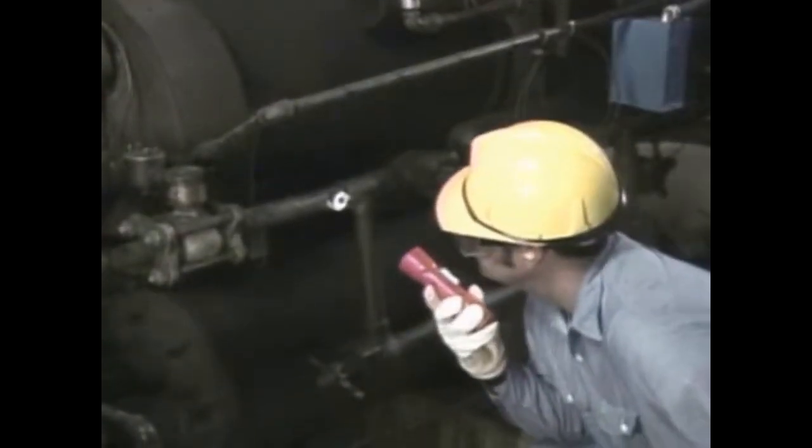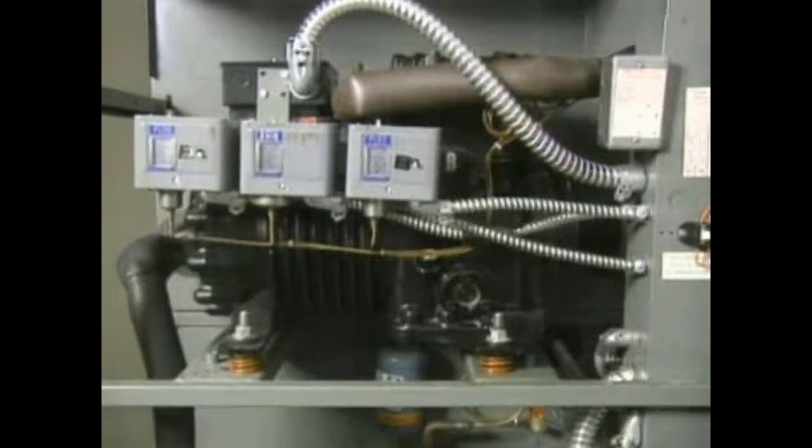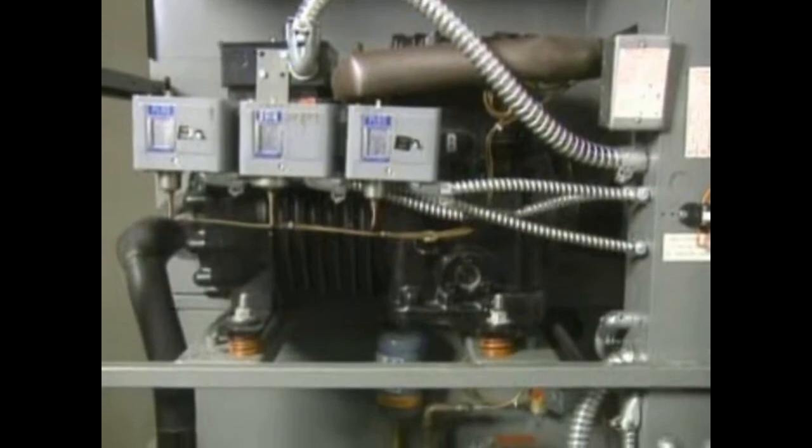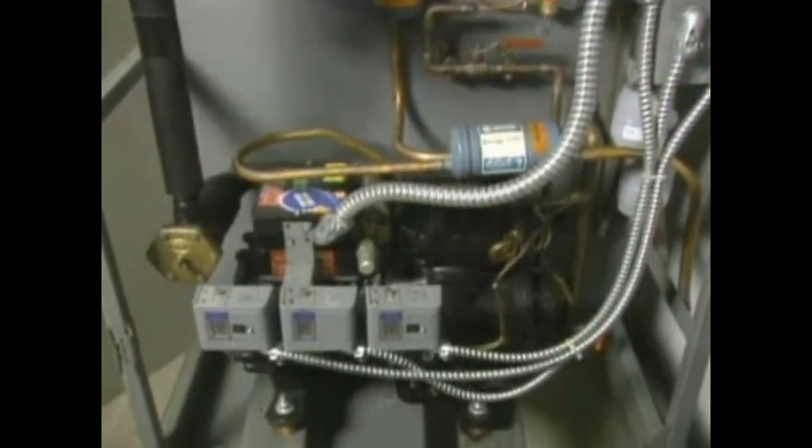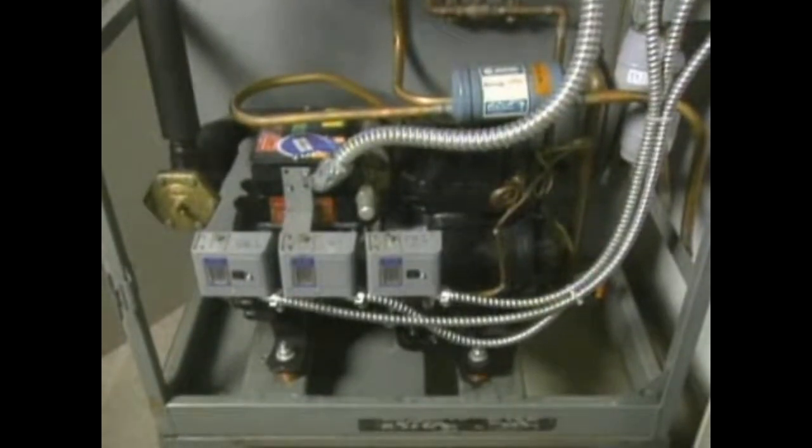When the amount of refrigerant in the system is correct, the refrigerant seen in the sight glass should be clear. If there's not enough refrigerant, the refrigerant may appear cloudy and it may contain bubbles. Another indication of too little refrigerant may be a continuously operating compressor. Some types of refrigeration systems cycle the compressor on and off to maintain the proper cooling. If this type of system has too little refrigerant, the compressor may run continuously, trying to maintain the desired amount of cooling.